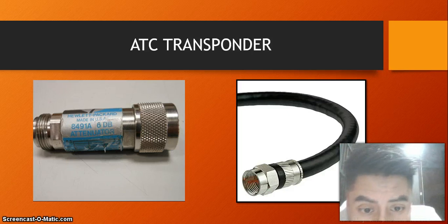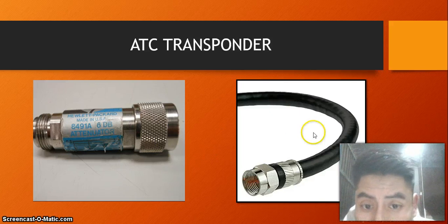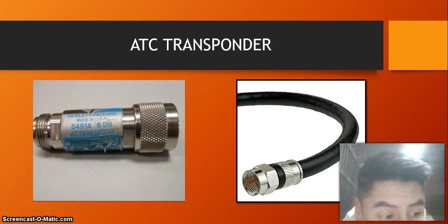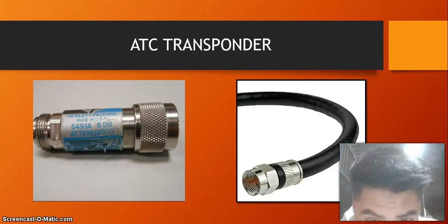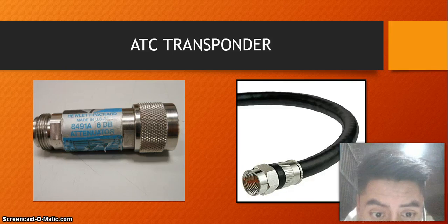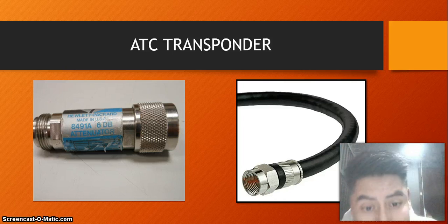Finally, the coaxial cable. This cable transports high frequency electrical signals. It has two concentric conductors: the central one called the core, responsible for carrying the information, and the outer one with a tubular appearance, which serves as a reference for ground and the return of the currents.